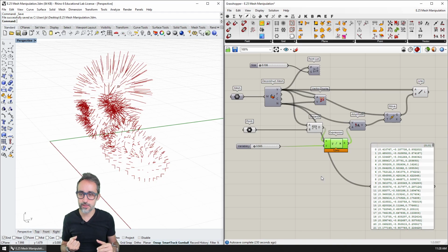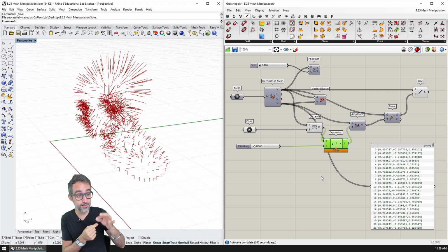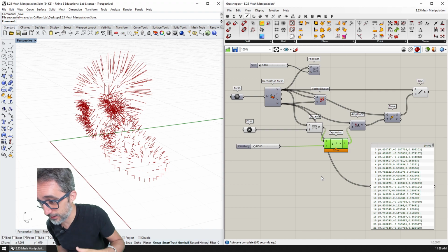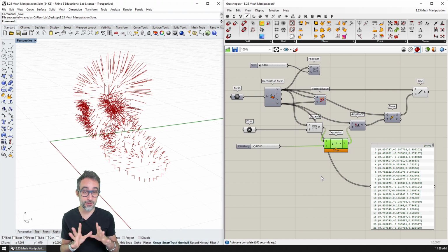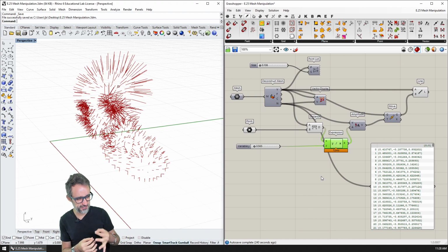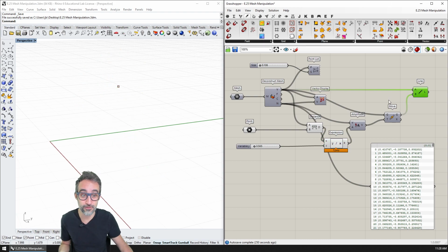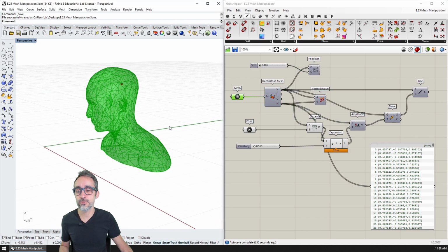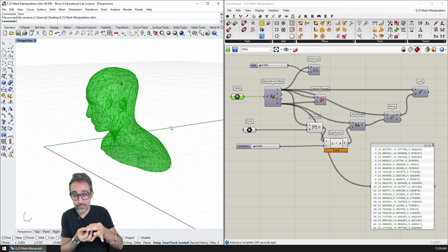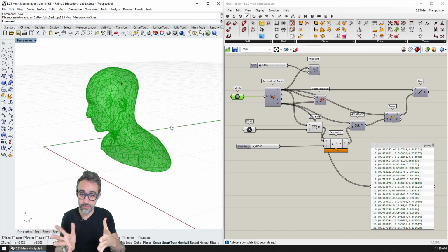Now, back in Grasshopper, what I could do is create that line, right? But as you have seen in previous videos, and if you know me already, I would like to do something a little more parametric than just a line. And also it's a good thing if I teach you something new. So if I have my mesh, I can create a bounding box around the mesh to figure out what is the line that fits perfectly this head here.